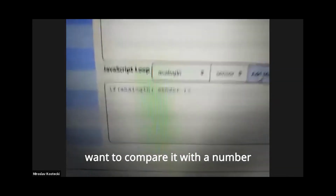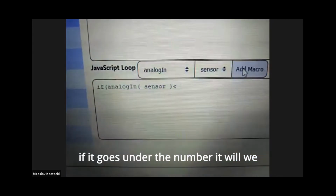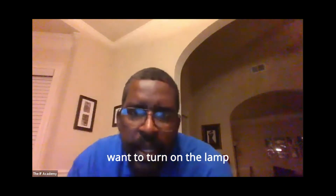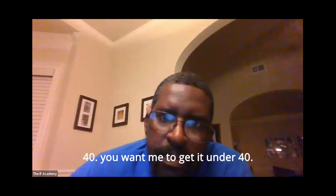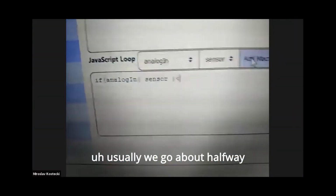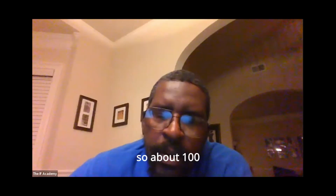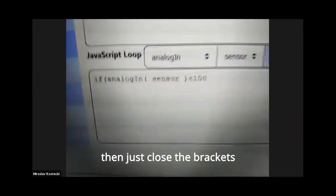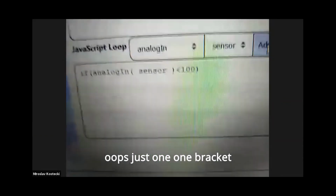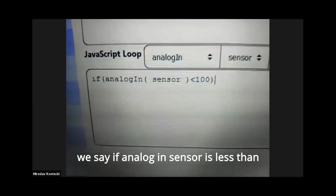So if we say we want to measure it, I want to compare it with a number, which number do you think we should use? If it goes under the number, we want to turn on the lamp. If it said 34, let's say 40. 40, you want me to get it under 40? Usually we go about halfway. So about 100? Yeah, okay, that's fine. All right, 100, and then just close the brackets. Oops. Just one bracket, and that's it. Just press enter. So we say if analog in sensor is less than 100,